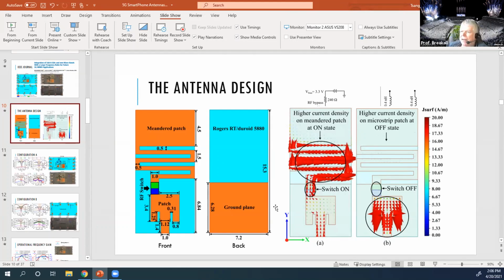The other thing, if you look at this, when you showed the currents there, this is actually a perfect slide. I don't understand why you would have all that extra metal up at the top, where it says meander patch on the left, when it doesn't look like any currents ever go on that.